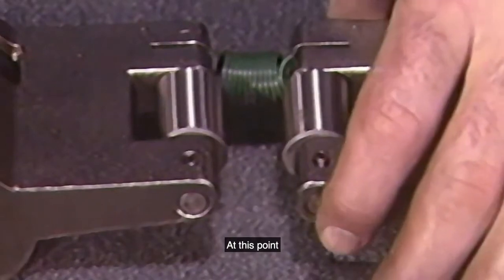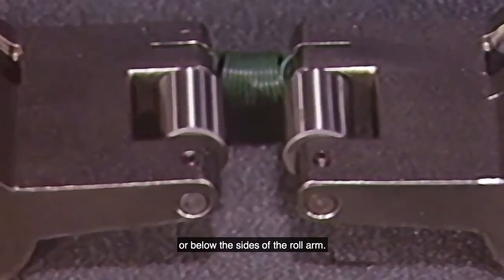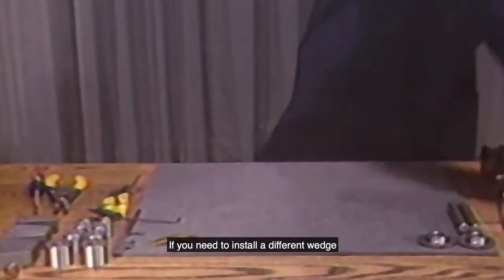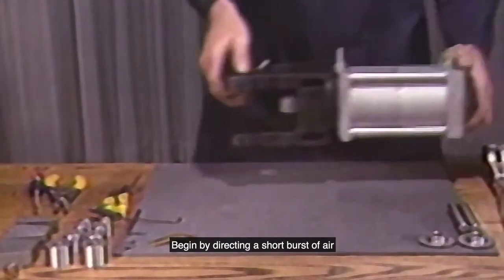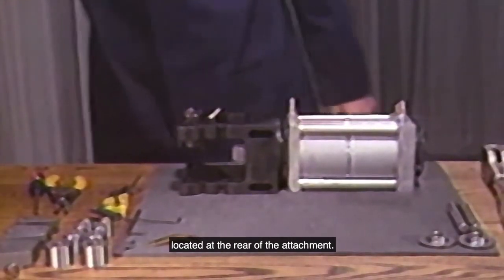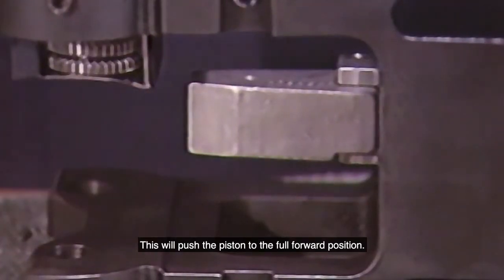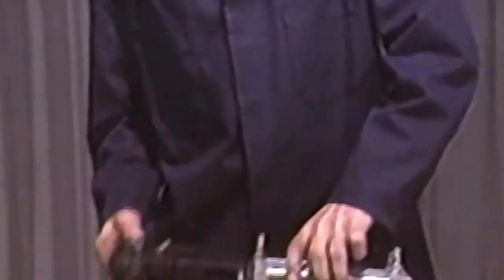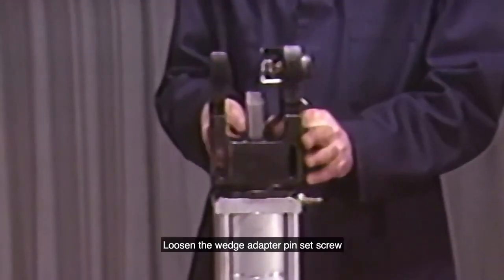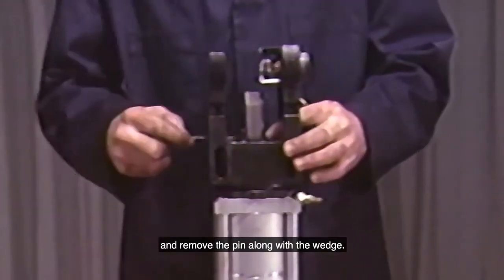At this point, each end of the wedge roller pin must be flush or below the sides of the roll arm. If you need to install a different wedge, begin by directing a short burst of air into the quick disconnect sockets located at the rear of the attachment. This will push the piston to the full forward position. Loosen the wedge adapter pin set screw and remove the pin along with the wedge.